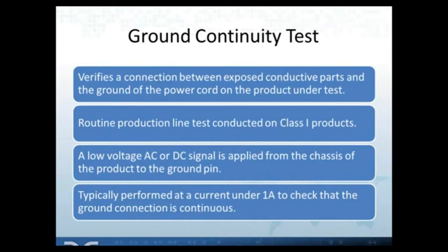We all know that grounding electrical equipment provides a second line of defense against electric shock over and above the basic insulation of a product. And this grounding of the metal enclosures or exposed dead metal on the equipment also establishes a common ground or earth reference between multiple pieces of equipment which may be in close proximity to each other.